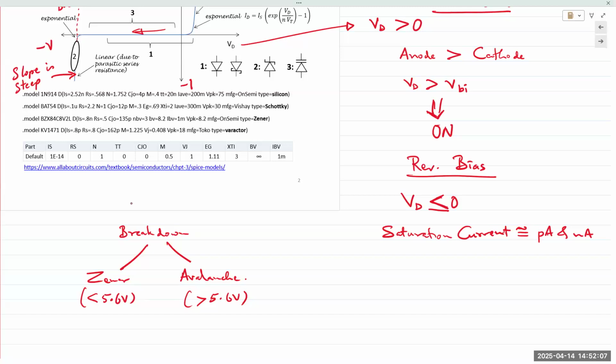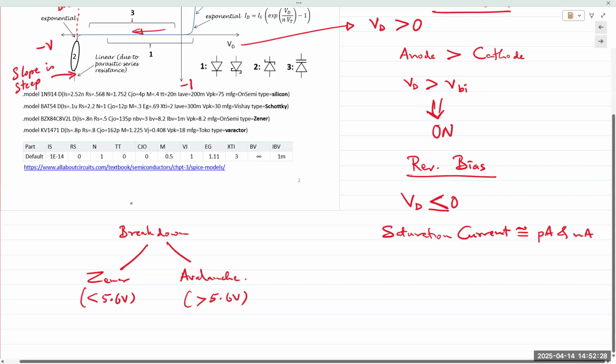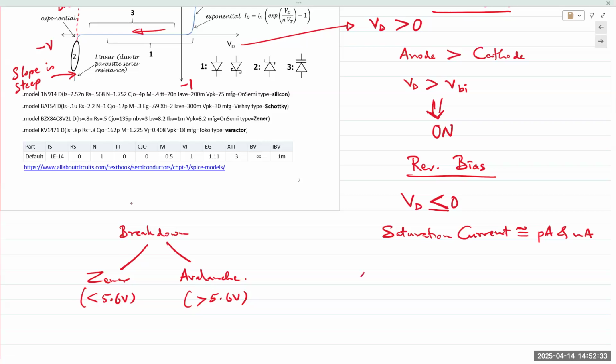Now, typical diodes that we operate, let's see, the 1N4000 series. Have you all used that diode before? 1N4000? It's like a black encapsulated cylinder with a gray silver band at one end. You'll use it in 215, I mean 245 perhaps. Okay. No, not the Schottky ones. These are regular silicon diodes. And 1N4000 ones are the most common ones you'd find in any AC to DC rectifier circuit.